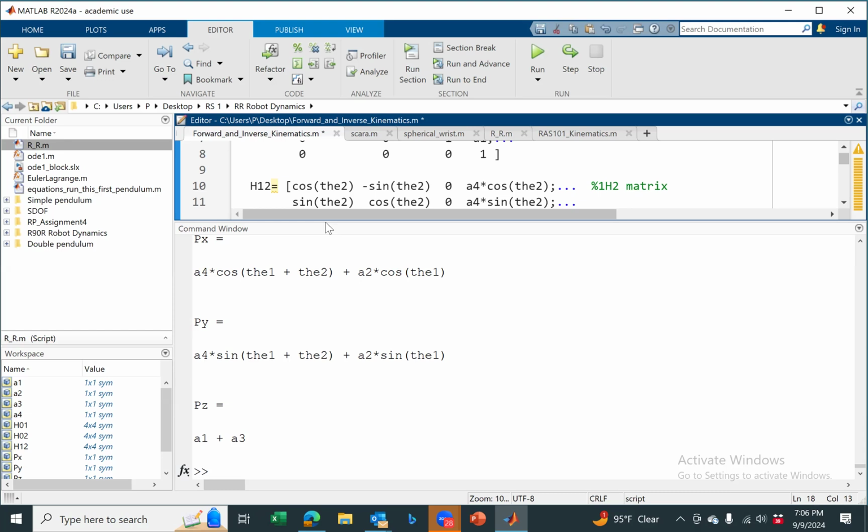This is not the only way to solve the problem. But what I want to do is, I want to solve a forward kinematics problem, get the solution of that forward kinematics problem, and solve the inverse kinematics problem. That's why the code that I'm gonna show it to you is slightly twisted. And the only reason for this is I'm solving the forward kinematics problem. I'm capturing the solution of the forward kinematics problem, feeding it back into the inverse kinematics problem, and seeing if I'm getting the same angles that I substituted.